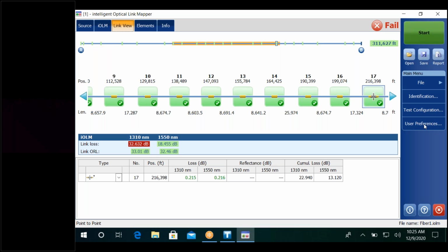The only difference is with every OTDR trace, you're given information, right? This was the pulse width. This is how long we did it. That was the distance. Because this used variable pulse widths and it did multiple acquisitions, you're really only going to get a trace or a graph that is an interpretation of these results. So you're not going to see a pulse width. You're just going to see a graphical view. That's helped people too. So at the end of the day, it just becomes preference.